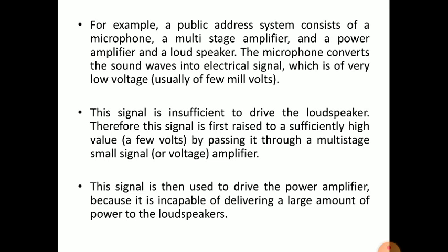They will be converted into low energy electrical signals, which are given to the input of multi-stage amplifier, which has to boost the power level of this weak signal, and it should drive to the end of the amplifier, where the power level is required to drive the output loudspeaker.